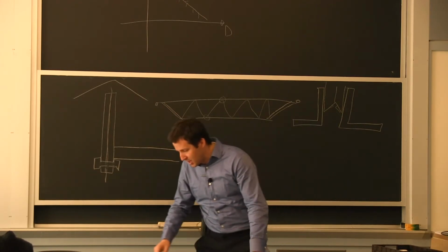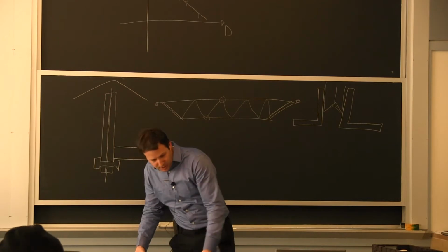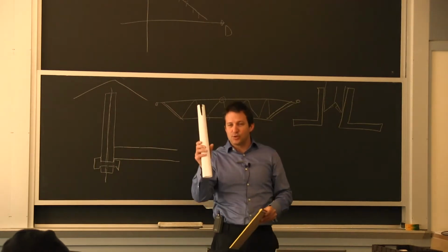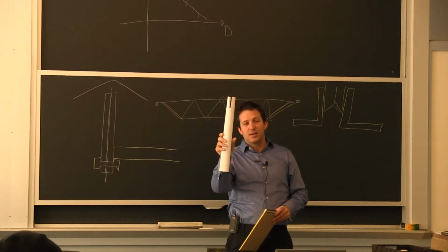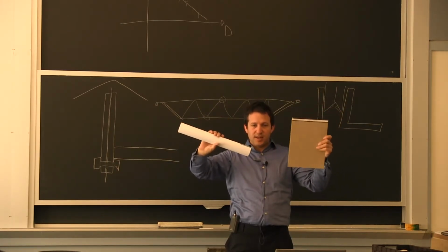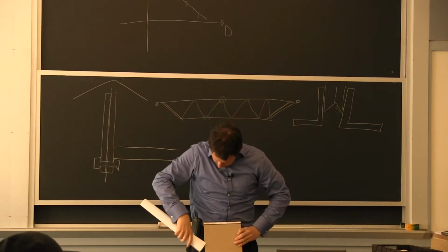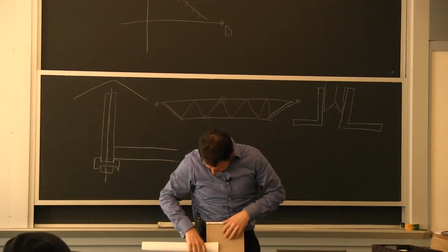Professor Eager mentioned gusset plates. I'm sure some of you know, but I want to make sure, so I built this one this morning. It's a tube. I made a notch in it. So all you do is you put it against the gusset plate, which is a flat plate, and then you come and weld. So it's just a linear joint.